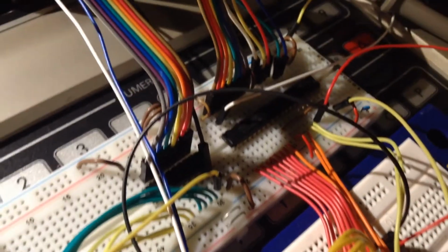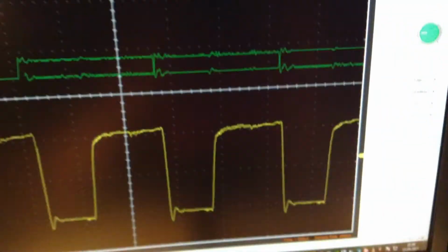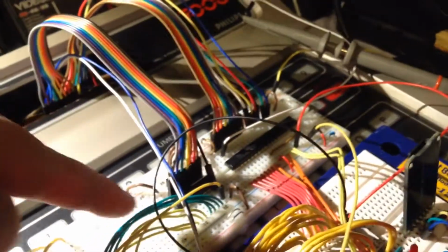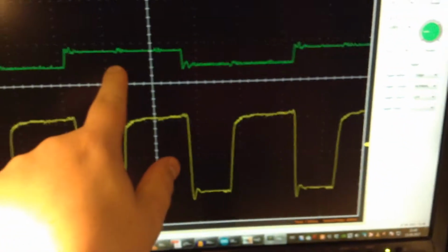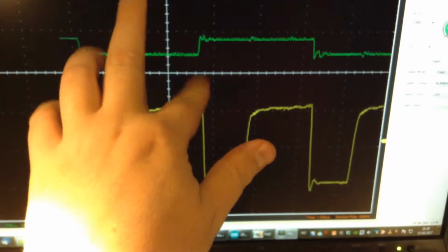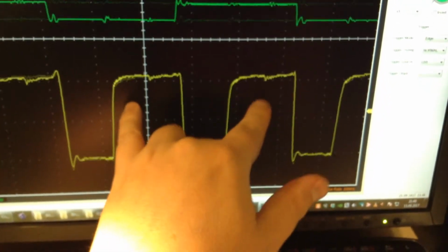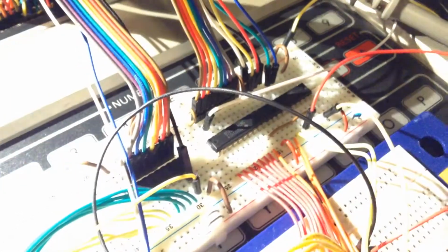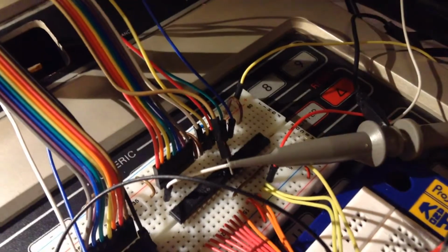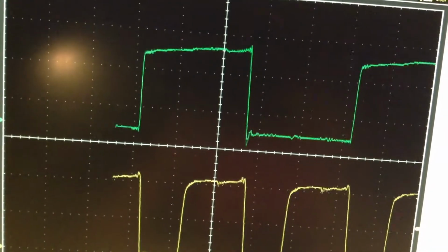I can't reproduce the problem I have, so this is the chip select, which is connected to the output enable of the data thing. And see how small this signal is. This is supposed to be address line 1, which normally changes for every clock cycle or every output enable. So you can see I'm measuring down here, and let's pick it up and see what happens. Now it's up in the air, you can see. Just hooked it up there, and the signal is back to normal, or something that looks normal.